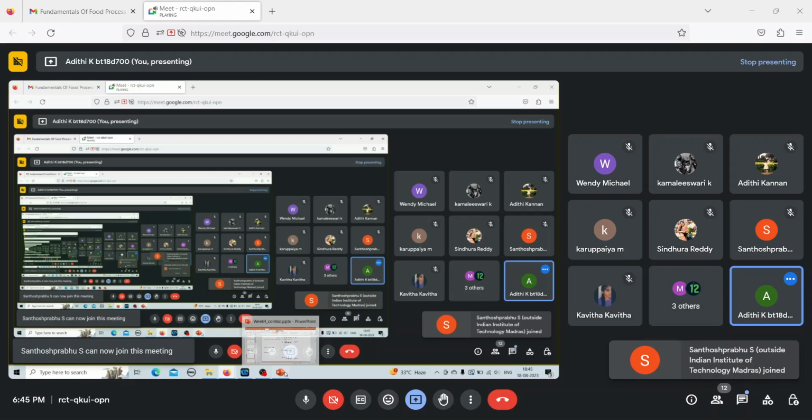That is steam temperature minus temperature of the evaporator, which is T1. And delta T2 is the steam temperature, but in the second effect you do not have a concept known as steam. It is the vapor from the first effect that is heating the liquid. So this will be T1 instead of Ts: T1 minus T2.